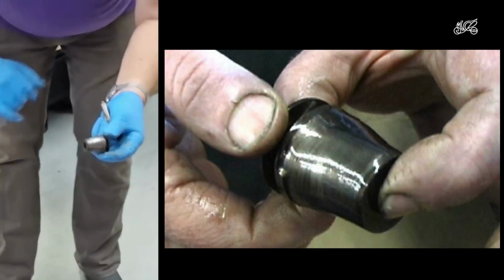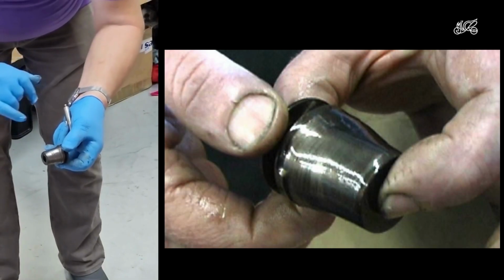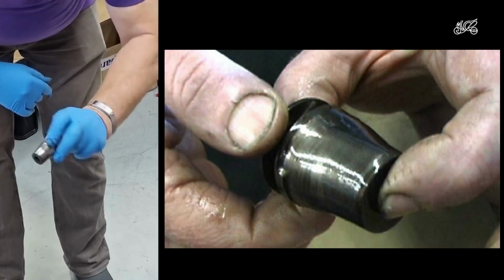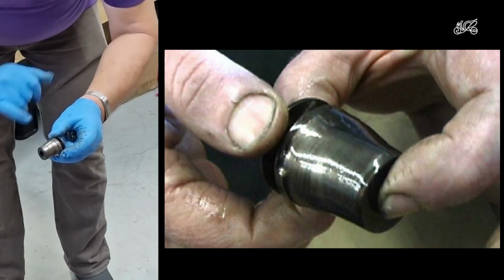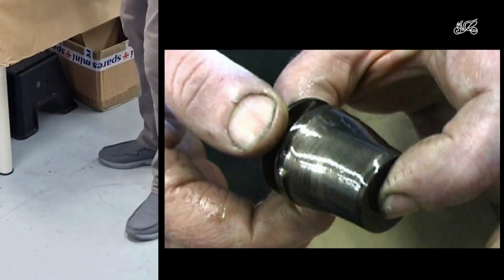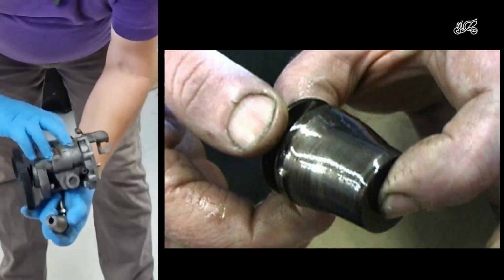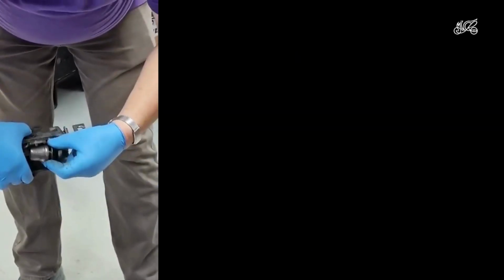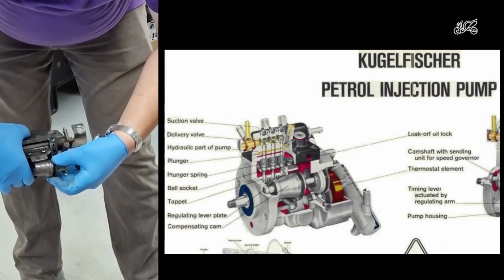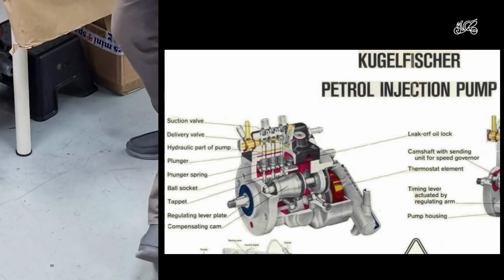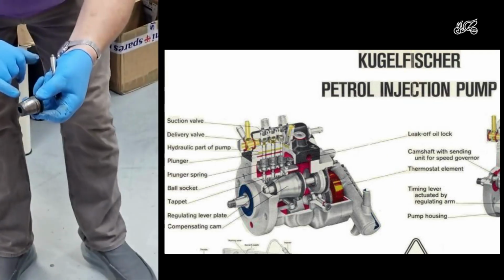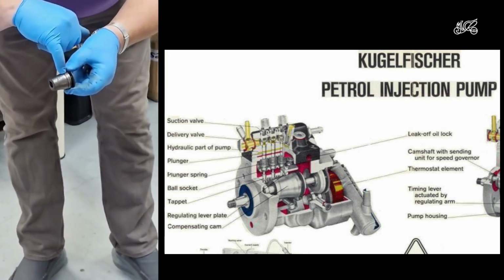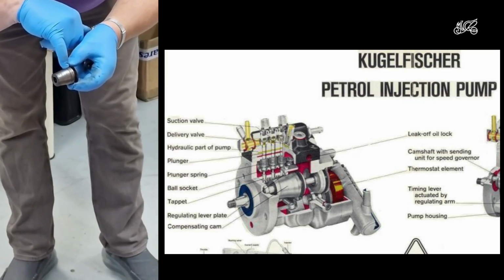So this thing, it's not in the engine. It's free to rotate about 270 degrees, and this plate has got a little nub on it, which rubs along this cone, and so this cone is a fuel map. So the highest point here is idle.